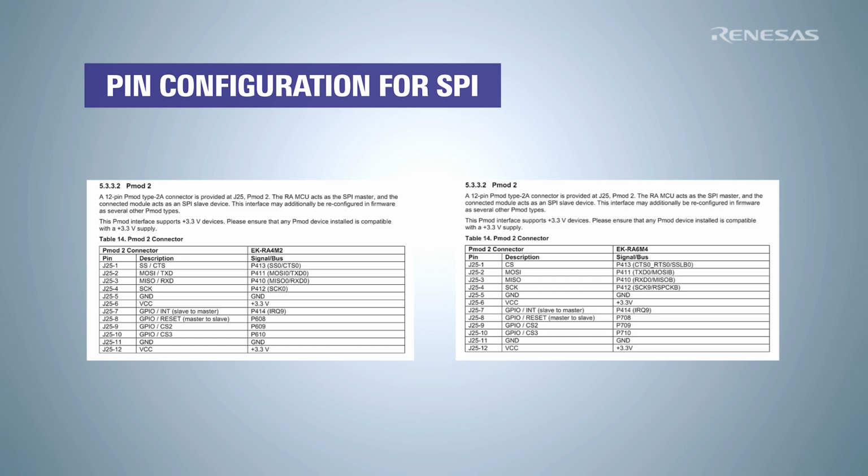The other possible configuration change has to do with assigning the correct pins to the PMOD2 stack. Now, the PMOD2 port is hardwired to specific pins on the board. So, we need to make sure those pins are correctly assigned for this new board, since the default SDK is made based on the pin configuration of the RA4M2.